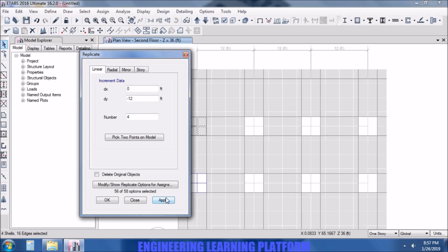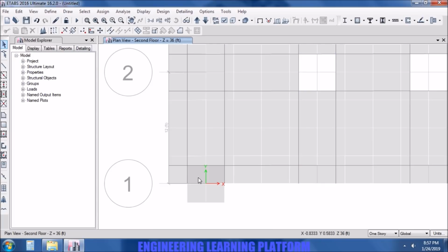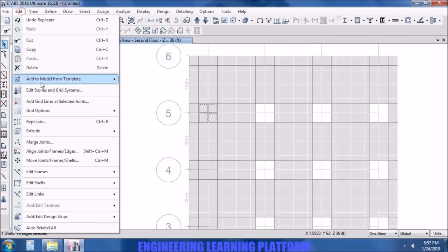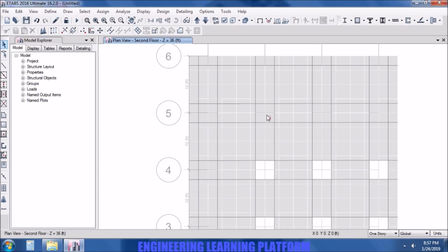So now we need to replicate the drops. So you see, I have added by mistake an extra drop which had to be deleted. So now replicating in other axis direction, giving it 3 numbers. When you hover the cursor over the apply option, it gives you a preview.